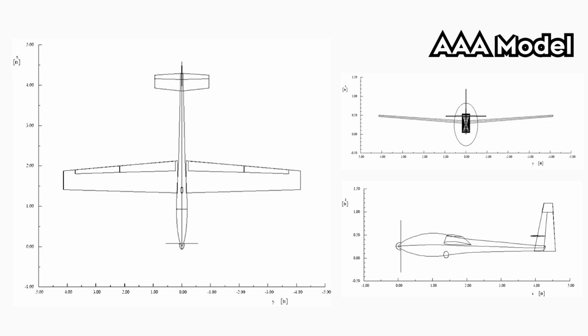It also has 2 control surfaces, flaps and ailerons. Flaps are high lift devices used in takeoff and landing, and ailerons are roll control devices. Between the 2 control surfaces, almost the entire wingspan is taken up by control surfaces, flaps, and then outboard ailerons.